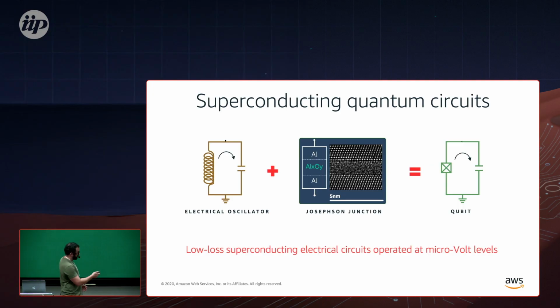So that's what we have to build in the lab. We have to build these kinds of electric circuits using microfabrication techniques. I'll show you a picture. There are three main differences from the way we do things these days. The first is that we need superconducting materials. A lot of the fab processes are not made for aluminum, so we have to develop processes that work for superconducting materials. That's one challenge. The most challenging part is building the Josephson junction. You have to build it as precisely as possible, because defects in the junction create decoherence for the qubits. We have to avoid this.